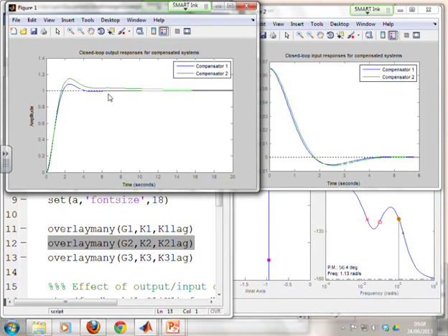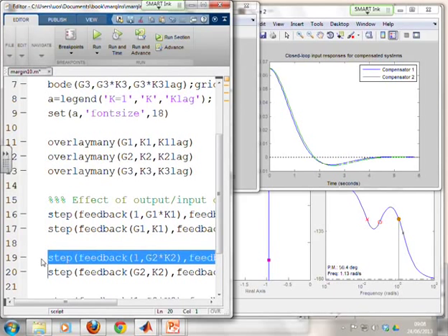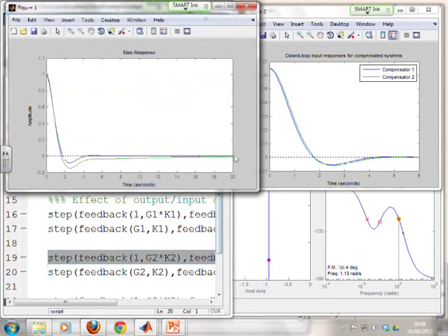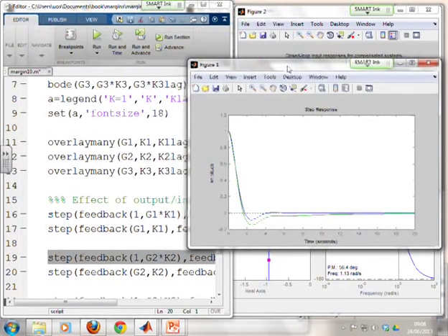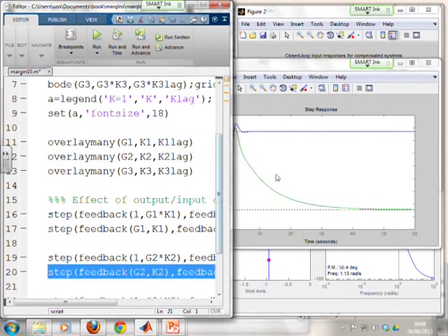And you'll notice here the system already had an integrator, so you might say, well, I didn't need gain recovery because I've already got an integrator. And so if I put in gain recovery, it's just made my margins worse and made my performance worse. So let's see where you might need this. If I now look at disturbance rejection, okay, what do you notice with disturbance rejection? Well, if it's an output disturbance, again, because there's an integrator, you still get zero offset, and again the simple gain design seems to have done slightly better. If, however, you have an input disturbance, what do you notice now?